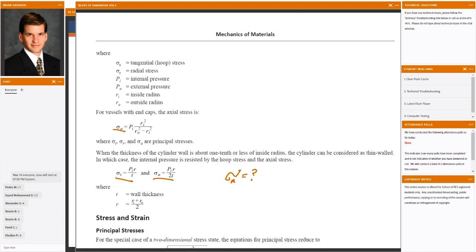It's just the pressure. In any of these pressure vessels, for example, if the pressure is on the inside, then this is the radial stress on the inside of it. It turns out that pressure gets sort of distributed out across the rest of it, and you'd end up with zero radial stress out here at the edge. So the radial stress actually undergoes a gradient from its high value matching the pressure here to zero out at the surface. Or you could say it averages out across the surface. So no difference in calculating radial stress for the thin-walled versions, but obviously the other two equations got less complicated.